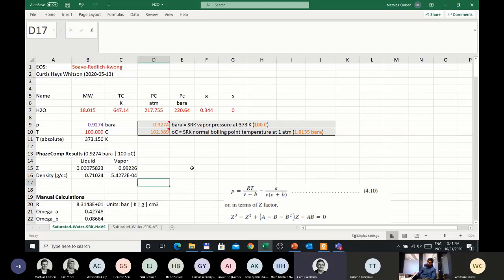So the compressibility of water, every petroleum engineer knows, is important in terms of getting water influx correct, well test analysis correct. Getting the water compressibility is a very important property. And you basically can't get it from this cubic equation of state the way it's used now, where we tie the A and B to the critical properties. Now, the critical properties are not of interest, right? 647 K is a very, very high temperature. We're never going to be close to that.